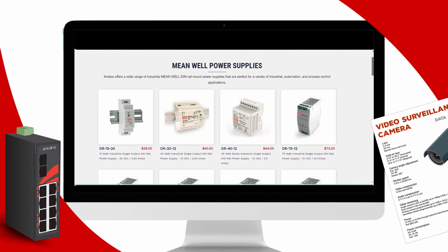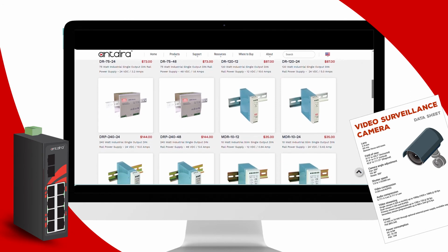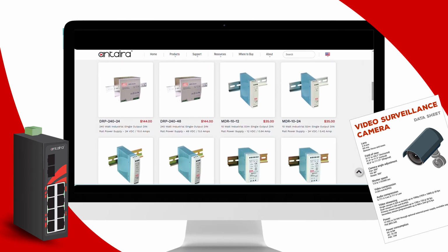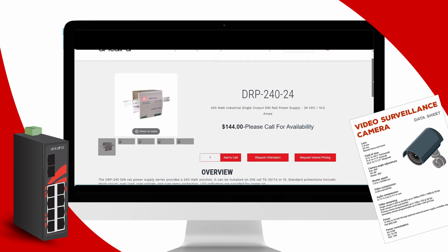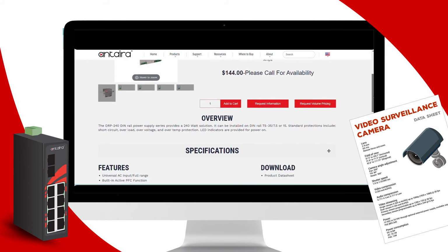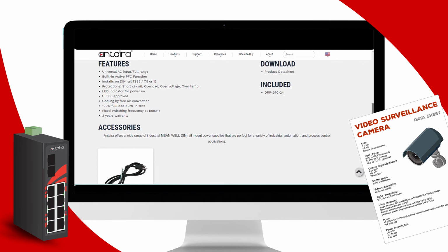You can see that doing a little research on the devices being powered can result in a much smaller power supply. The power supply that can provide up to 300 watts could be 3 times the cost of the smaller power supply and can take up to 2 times the space in your panel. This can have a huge impact on the cost of your project.